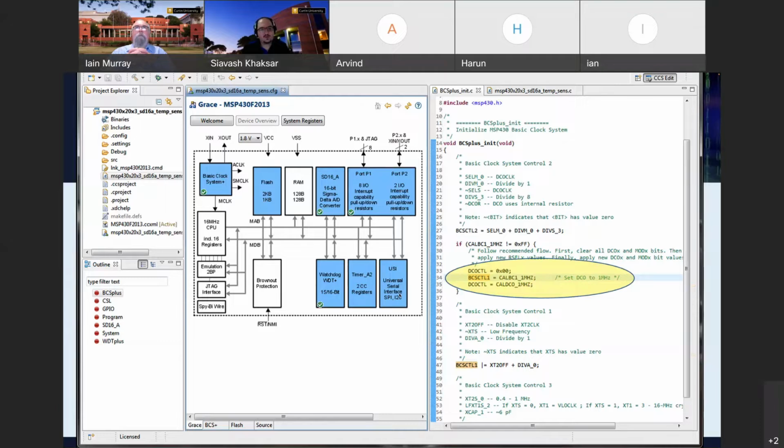Because this is such low level control, if you want to write very optimized code, you need to go one level lower than C. In this case, the highlighted part is that you go to assembly and mix C and assembly together in some instances. That can be specifically for those low level memory control setups when you're setting up your low power modes to handle the interrupt component, and that's something we can't necessarily do with the Arduino IDE. Now, with their 2.0 version, they have started adding these control register monitoring features.